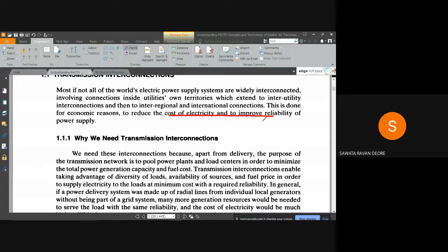You might have heard the words base load power plant and peak load power plant. Base load means those working continuously for 24 hours, given priority as per the economic generation scheduling which we studied last semester. So hydropower plants are given priority to operate continuously, and whenever the demand is greater, during that peak demand period thermal power can be utilized.